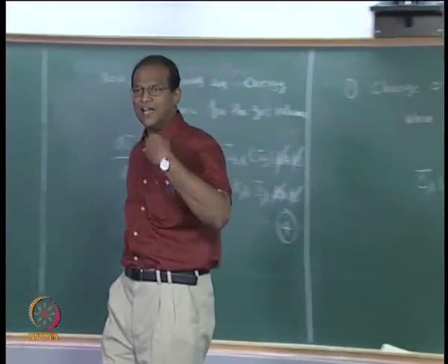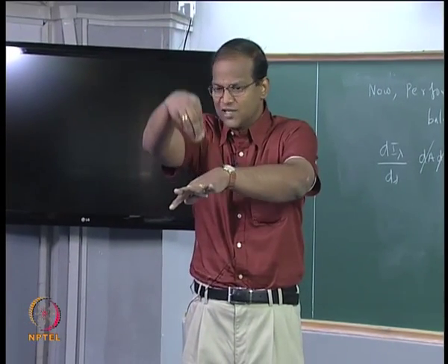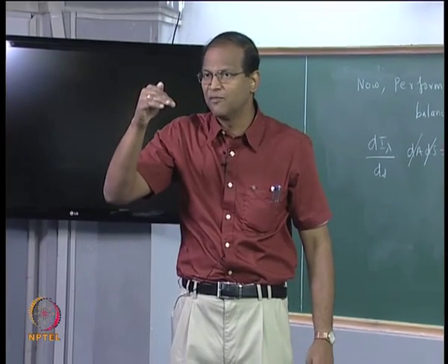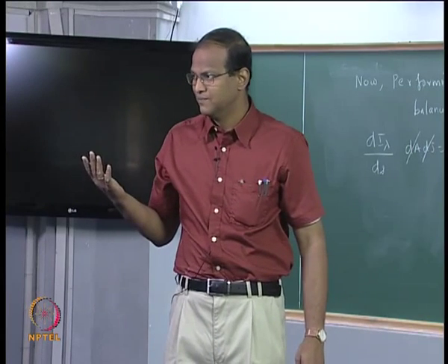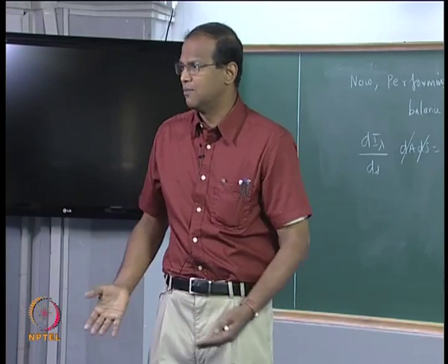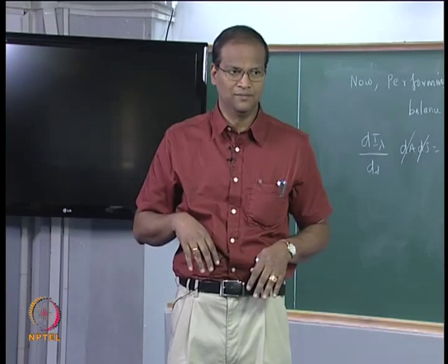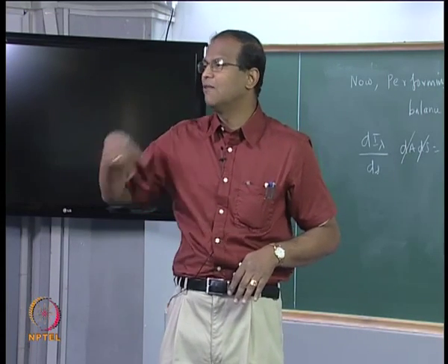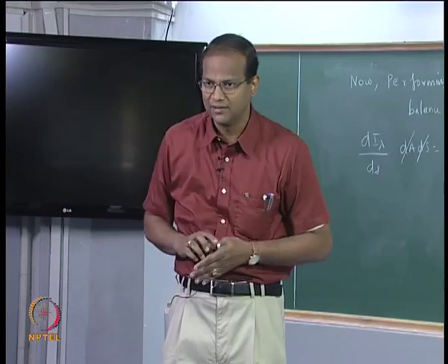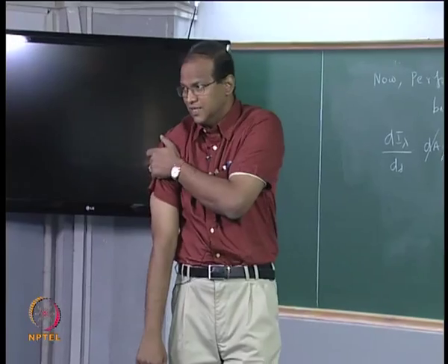When it is absorbing, I am saying that I lambda will decrease. I have a sheet of water, I am shining radiation on this. Obviously, as the radiation goes through, the bottom layers will get less radiation. In that case, what will happen to I lambda from the surface? It will exponentially decay. So it decreases the intensity which is coming out because some of it is absorbed. If 100 enter, 95 comes out, 5 is held back. But that 95 can be compensated, it can become 97, 98 or even 105 if there is an emission from that gas. Correct? That is a change, yes.